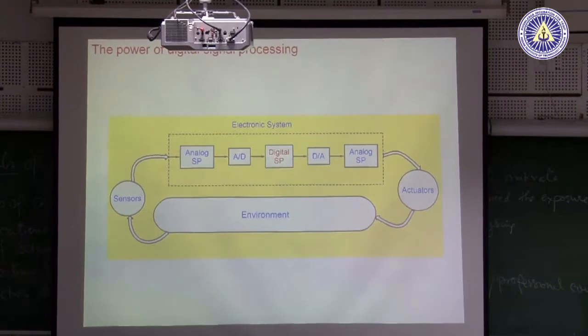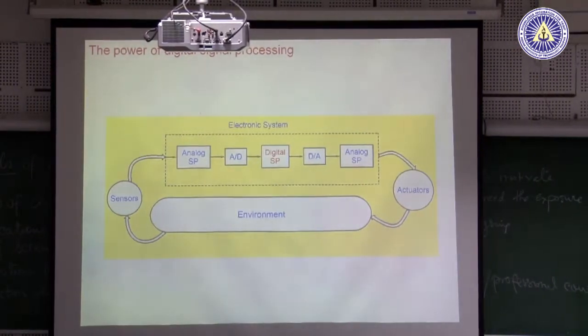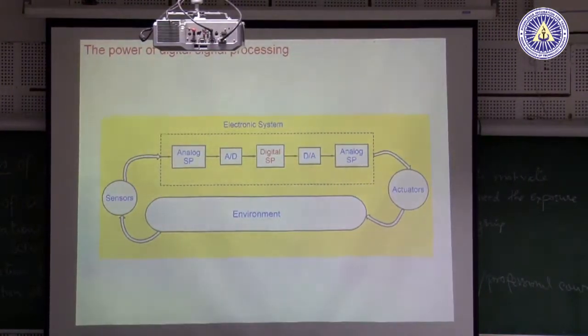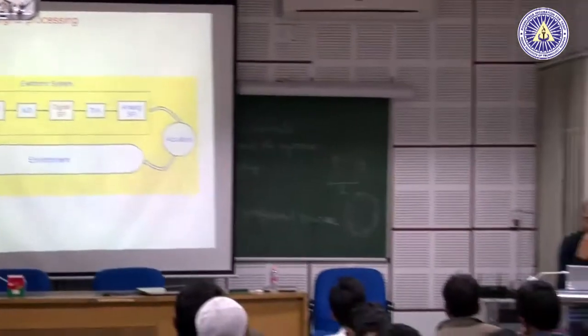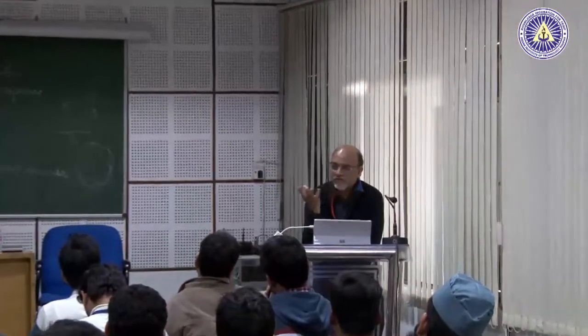Now, analog signals are a little bit hard to process. You can amplify an analog signal, fine. If you want to do an integration on that analog signal, you can; many of you may be familiar, you can build an integrator, you can build a differentiator, maybe you can multiply two analog signals, but it's not very easy multiplying two analog signals. If you want to divide two analog signals, take a log of a signal, or solve a differential equation, pretty soon you find things become difficult.